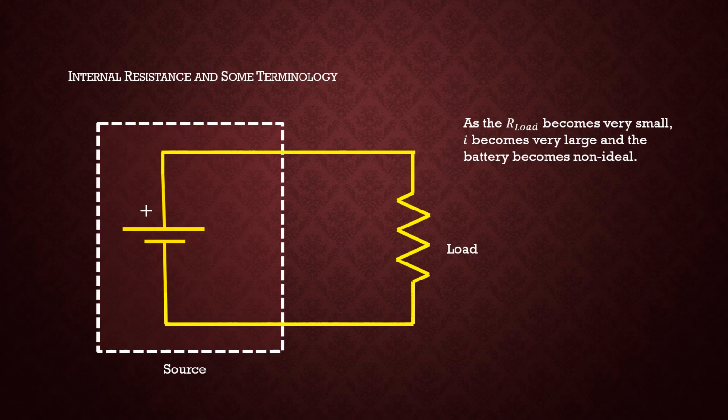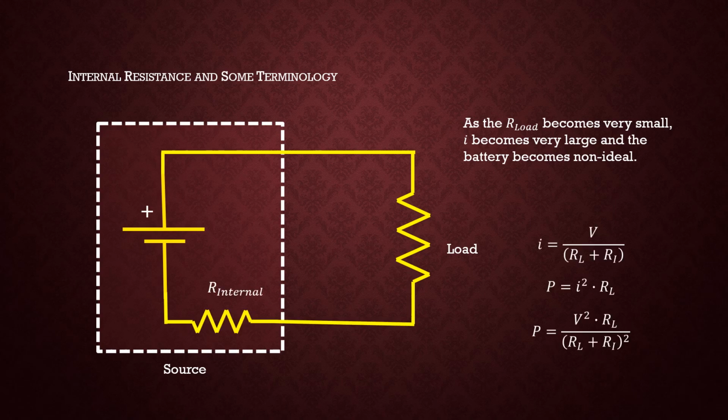Schematically, I would probably represent it this way. I would just draw a box around the voltage source, and I would distinguish the source, namely the power supply, from the external circuit, namely the load. So this would be like a cartoon type representation. I would embellish that cartoon by including an internal resistance, and then I would revise my Ohm's law for the circuit as indicated on the right-hand side. So the current would be limited by the modified denominator. The power would likewise be limited by the inclusion of that second internal resistance in the denominator.